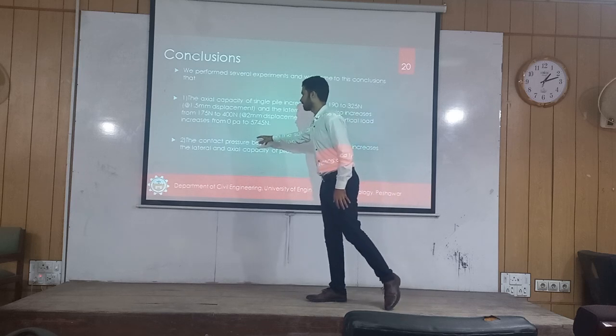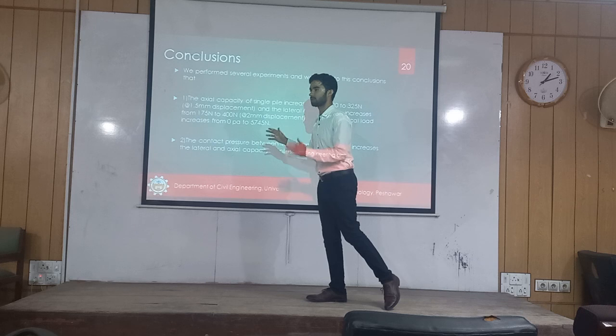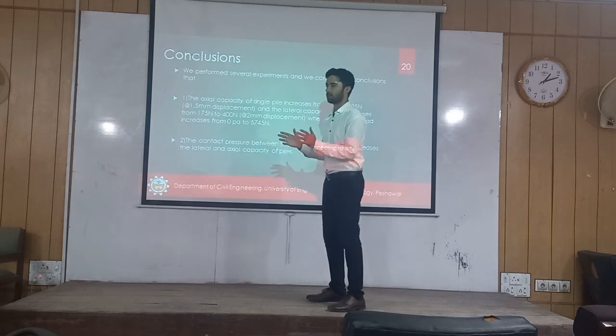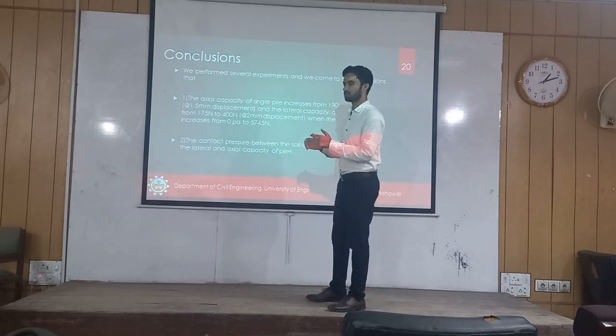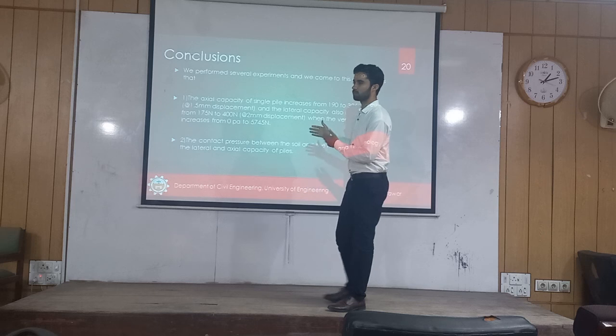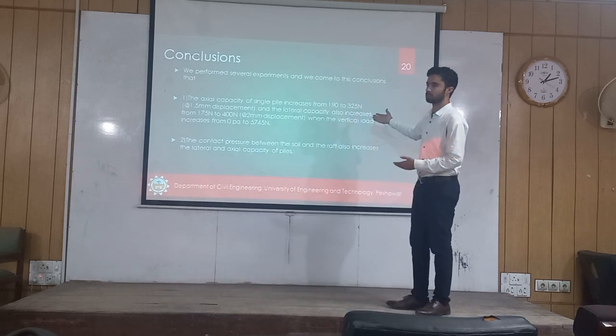This was our aim, to find what the effect of contact pressure on the pile is. So we come to this point that in the presence of contact pressure, the strength of the pile increases. When the strength of the pile increases, the displacement reduces. This is what we find, and this is what the experimental results show us.